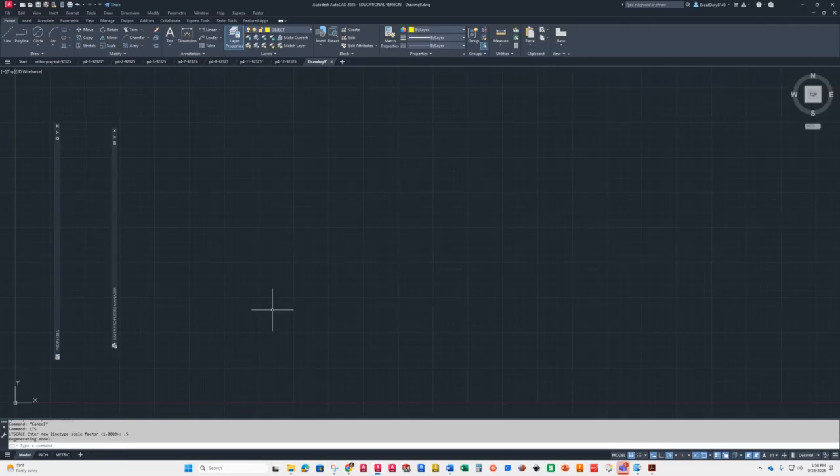Okay, so this is an old drawing. You know how I can tell? Because it has the word through on it. We don't use that. If it doesn't go all the way through, we put a note that says it has a depth. So don't ever put through when you're dimensioning, because that's wrong. It's an old practice, so we don't do it. Just leave it off. It would be the incorrect, outdated way of doing it.